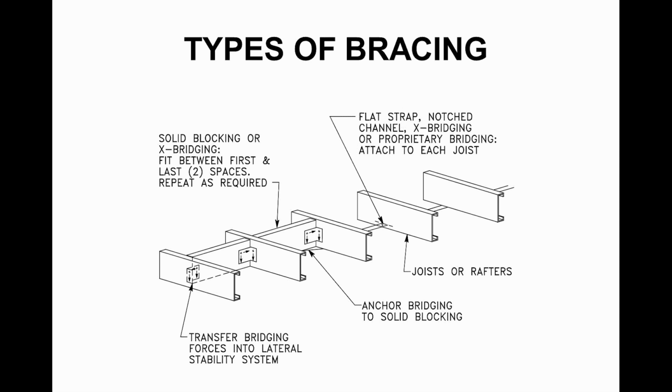What constitutes a member brace? Very important, because we talk about bracing. Cold form steel members are very light. Because they are light, they're flexible. Because they're flexible, they tend to buckle very easily. I need bracing. If I look at a floor system, I'm going to have sheathing attached to the top flange. Bottom flange may have sheathing or sealing, or it may not. If it doesn't, I need to provide a minimal amount of bracing on that bottom flange as well.